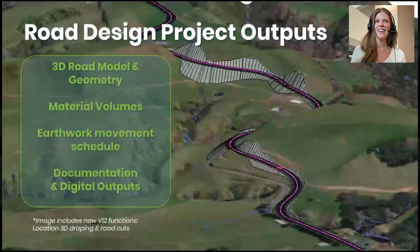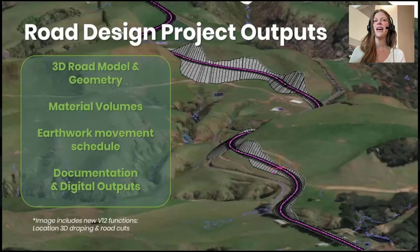And from there, we're going to be able to get a road design project. And those outputs that can come from it are our 3D road model and geometry. We can get our material volumes. If we're working with more than one material, we can get material volumes by specific material. Of course, you're going to get an earthwork movement schedule telling you how this material is being moved to construct your project. And then, of course, there's the documentation and the digital output side of things.